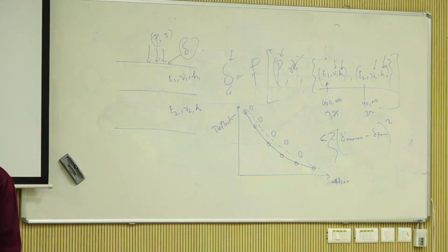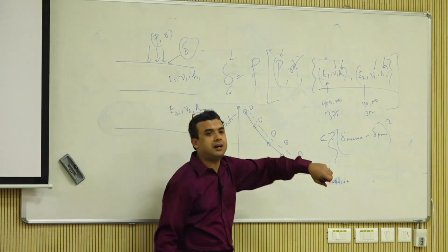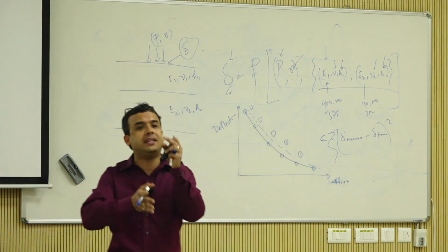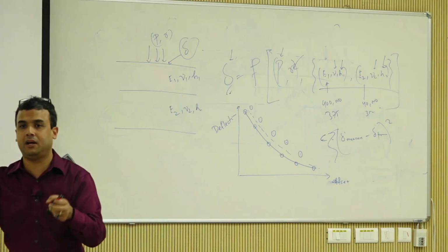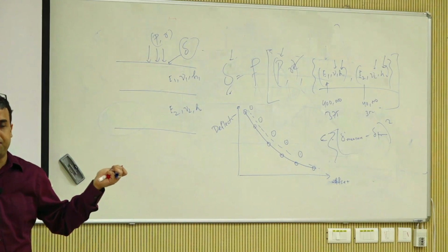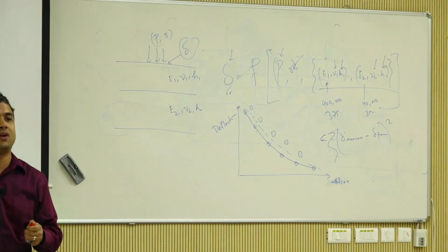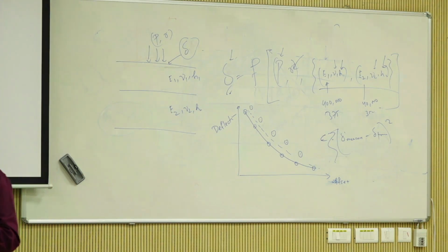So that's back calculation. There are many software packages available. Most of them have some kind of layered elastic analysis program in the background, and how they differ is the way they minimize errors, the error minimizing technique. A very common question is which is the best software to use. The very good answer is the software that you know how to use the best, right? It's not about which software, it's about how good you are at using whatever you're using. You can do the same thing with anything.